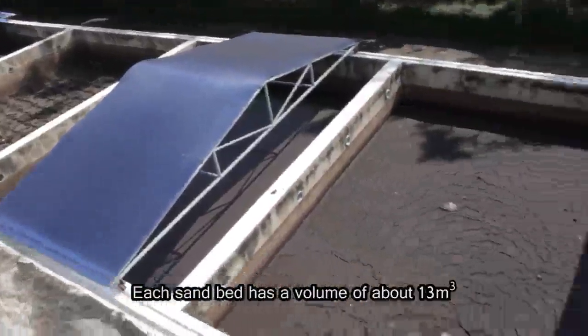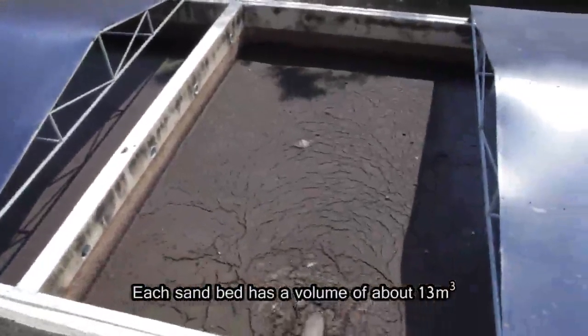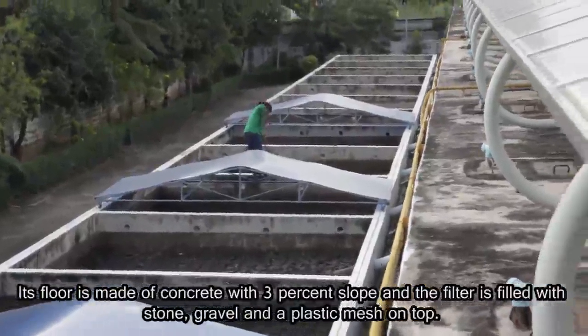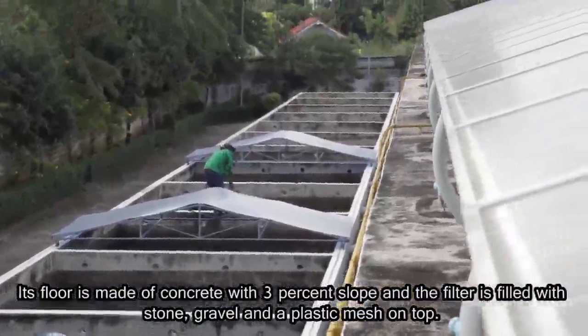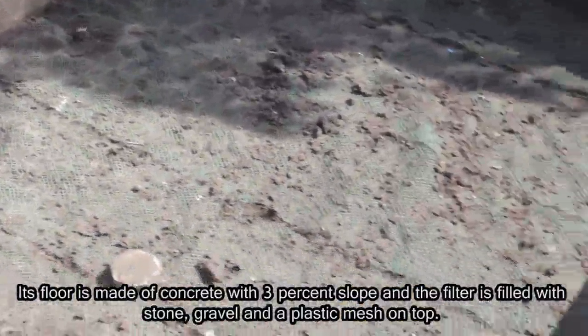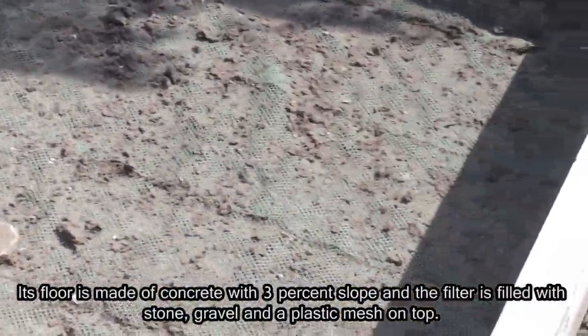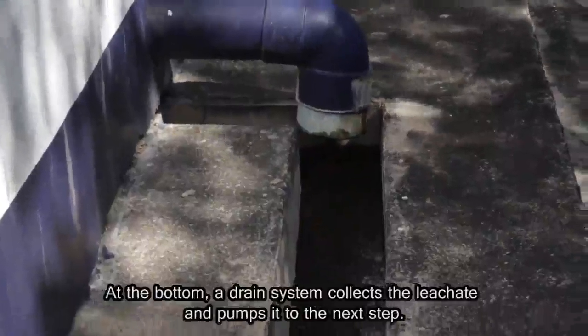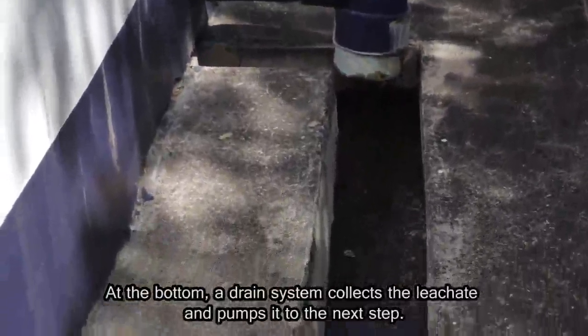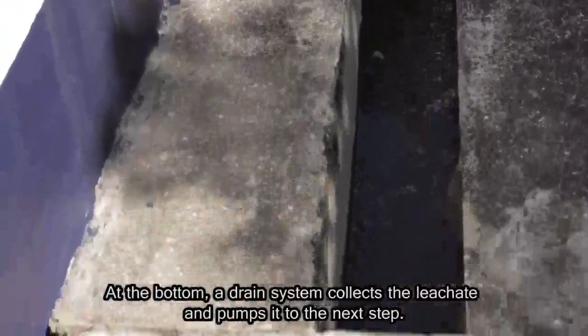Each sand bed has a volume of about 13 cubic meters. Its floor is made up of concrete with 3% slope, and the filter is filled with stone, gravel, and a plastic mesh on top. At the bottom, a drain system collects the leachate and pumps it to the next step.